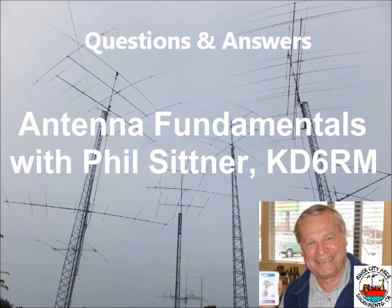Can you make it shorter by folding the end? Folding it back on itself? Sure. Yeah. So you can tune it by... One of my favorite tricks with dipole antennas was actually to cut them a little bit short, and then I solder a lead on the end of it to drop straight down. And then I could just snip off a little bit of it and save me having to rewrap them every time as you try to shorten it. And then you find out you cut it too short. It works pretty well. Make them a little shorter and put the tail on it.